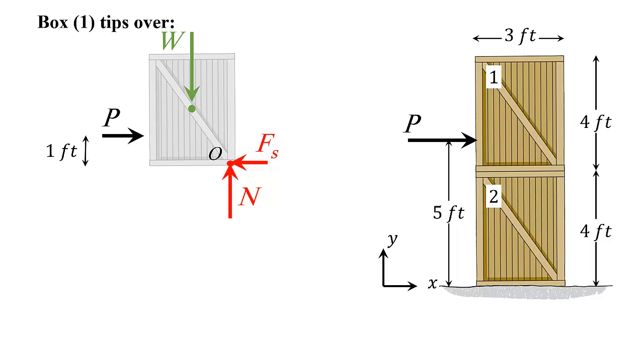With the system shown, with the forces, we can do the summation of the forces in the X, but notice here that P equals Fs, but Fs does not equal N mu12 because we don't have any sliding. In the Y direction equals 0, N equals W. But I cannot use these two equations by themselves. They don't provide that much information for me to solve the problem.